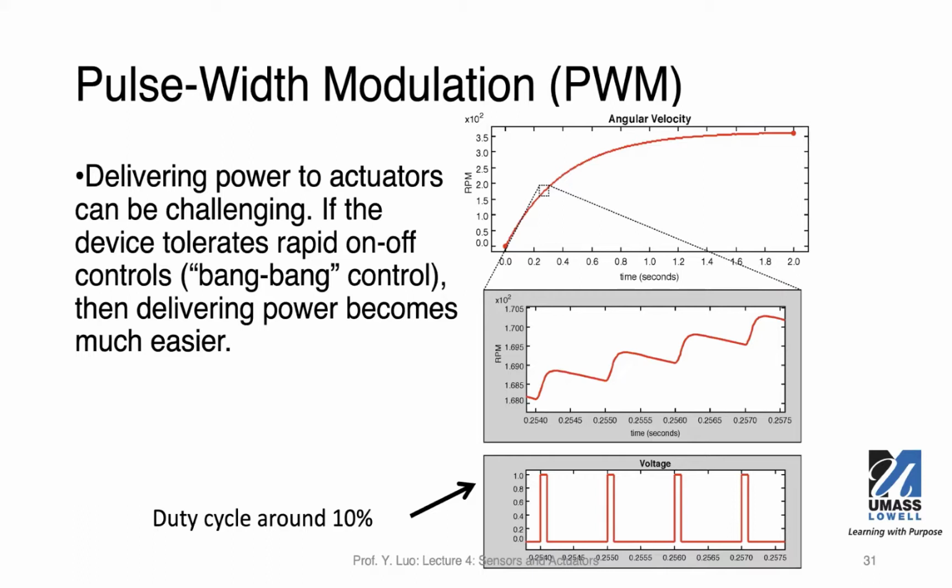So it's an actuator. You can turn this LED off, that means you just output a 0, and that'll be off, assuming that you connect the LED in a certain way. And you can turn this LED on by outputting 5 volt. So that's easy to do.